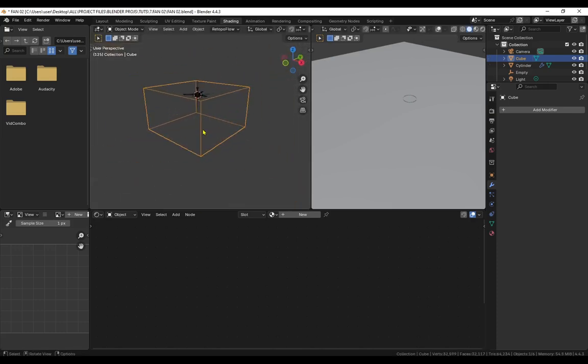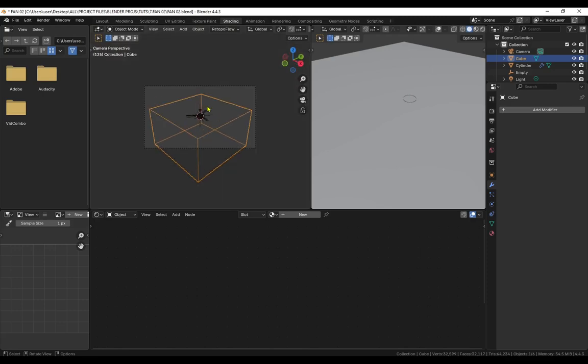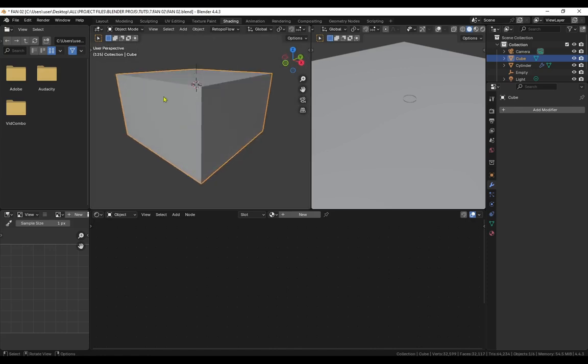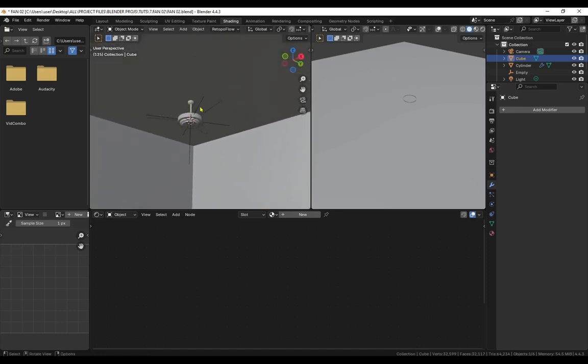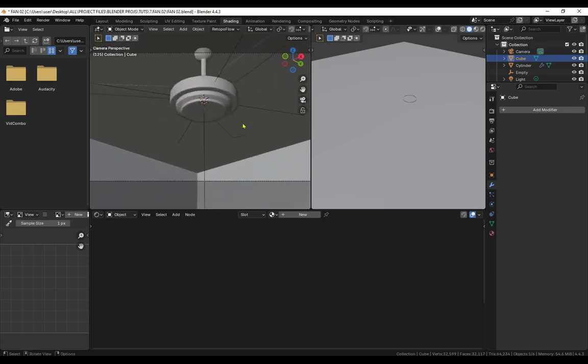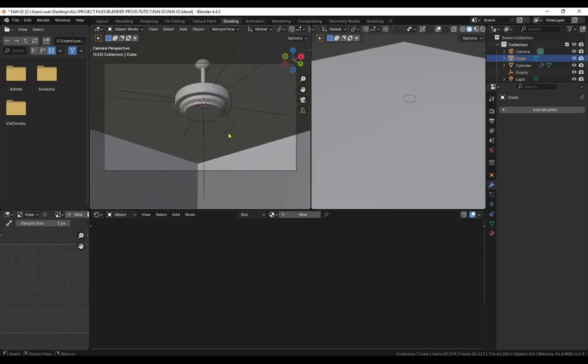And then let's move to the camera view. So you can see that this camera view is not what we want. So what we are going to do is move the view to something like this, for the camera to capture. Then hold down Control and Alt and then Numpad 0, to capture from the view that you are in. So we are now in the camera view.